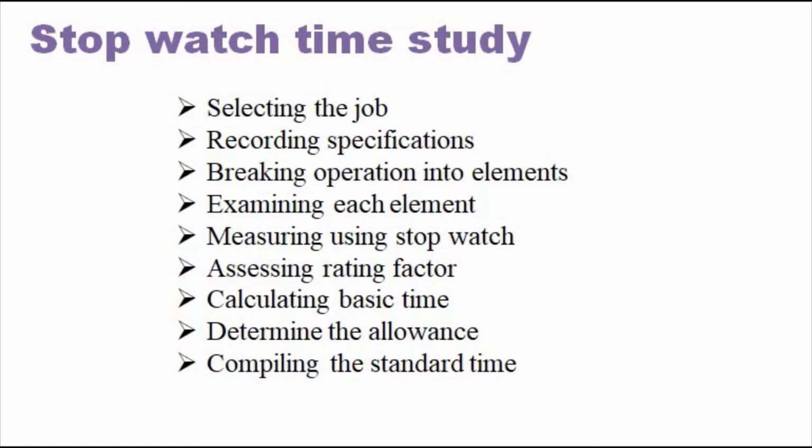In the first technique, that is stopwatch time study, these are the common steps that are generally followed. The first is selecting a job. The job is selected for which work measurement is to be carried out. Sometimes the job may be a new job, or the methodology is to be changed, and then the same job can be considered for the analysis.